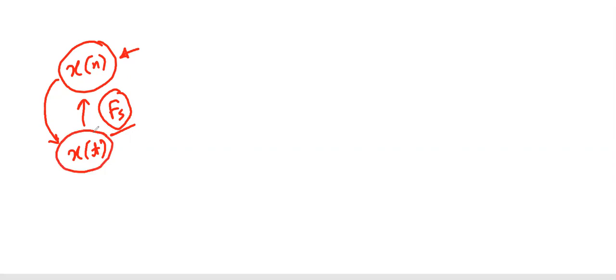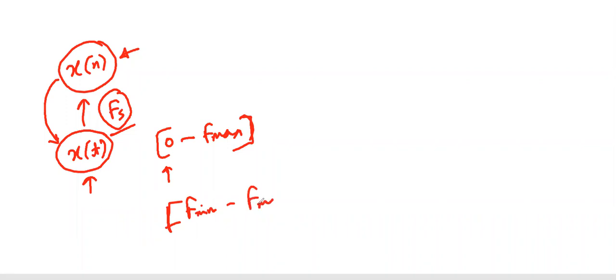As we have already mentioned, this analog signal x(t) may have a band of frequency. Let's start from the frequency from 0 to f max. Not necessarily always do you have 0 hertz there. We can mention it as f minimum to f maximum. So in that case, our sampling frequency fs should be at least twice the maximum frequency.